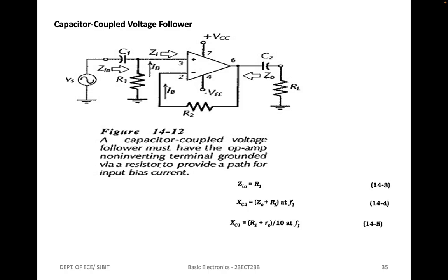Because the load is capacitor coupled, the DC output offset voltage might seem to be unimportant. However, the DC offset voltage at the op-amp output terminal can limit the amplitude of the AC output voltage. So, a resistor R2 equal to R1 should be included in series with the inverting input terminal to equalize the IB times RB voltage drop and thus minimize output offset voltage. Designing the capacitor coupled circuit involves the calculation of R1, C1, and C2.